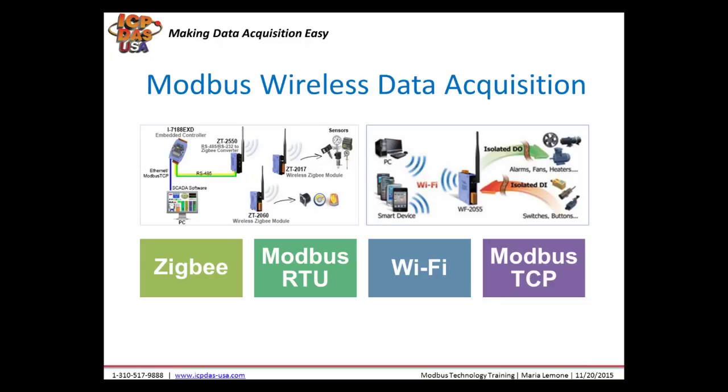Every Zigbee network needs a host converter so you can communicate back to a PC or controller. It sets up the communication path. The I/O are set up with some dip switches on the side so you can get them to be all on the same network and each one can have a unique address.